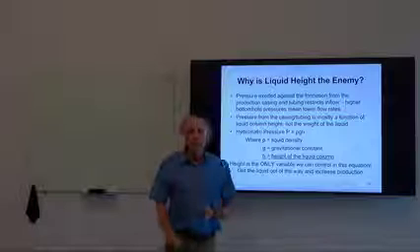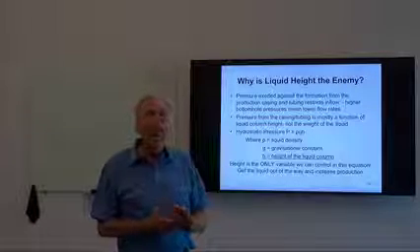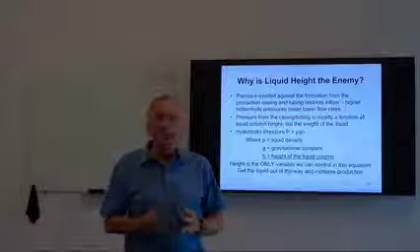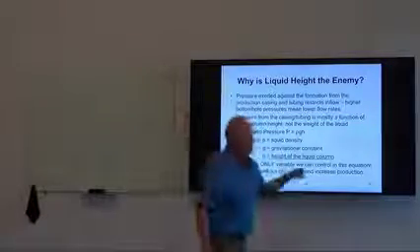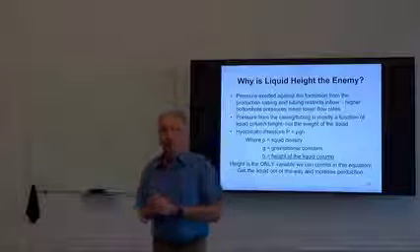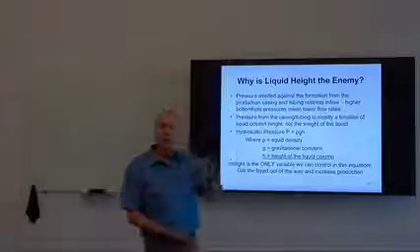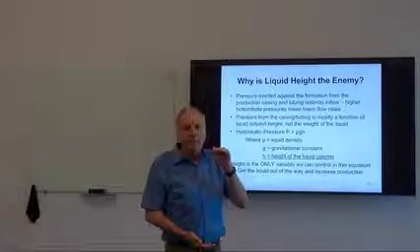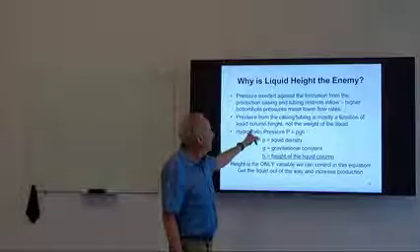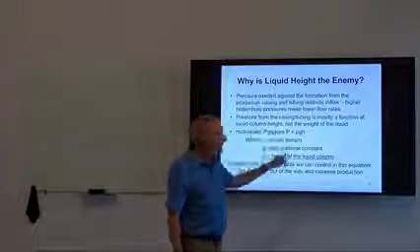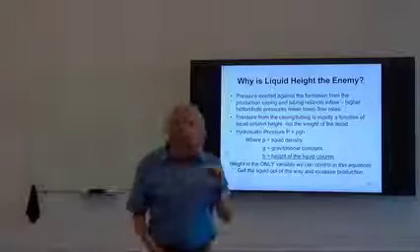Liquid density: the produced liquids do not change, or change very little, over the life of the well, typically. Gravity, the acceleration due to gravity, is obviously a constant, but the height of the liquid column could be highly variable. And that means that the majority of the variability in pressure P is solely due to the change in h.